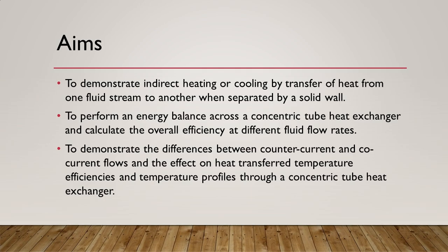This experiment aims to demonstrate indirect heating or cooling by transfer of heat from one fluid stream to another when separated by a solid wall. Through the experiment, students would understand energy balance across a concentric tube heat exchanger and the overall efficiency at different fluid flow rates under countercurrent and co-current flow conditions.